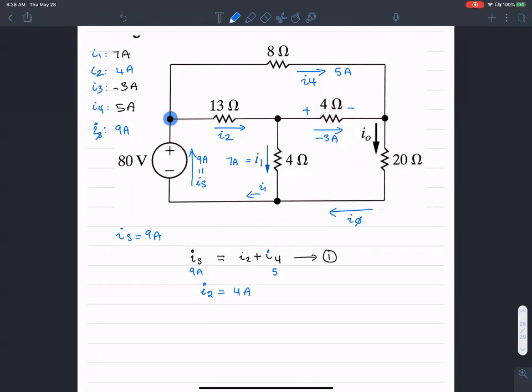Now that we know the currents across each component, are we going to find the voltage across each component? We could do that. It's just a product of resistance and the current. Or the problem goes on to ask you to find the power drop in each of these resistances. So you could do R times I, which is V, and multiply that by I, or you could simply do I squared R to give the value of power.